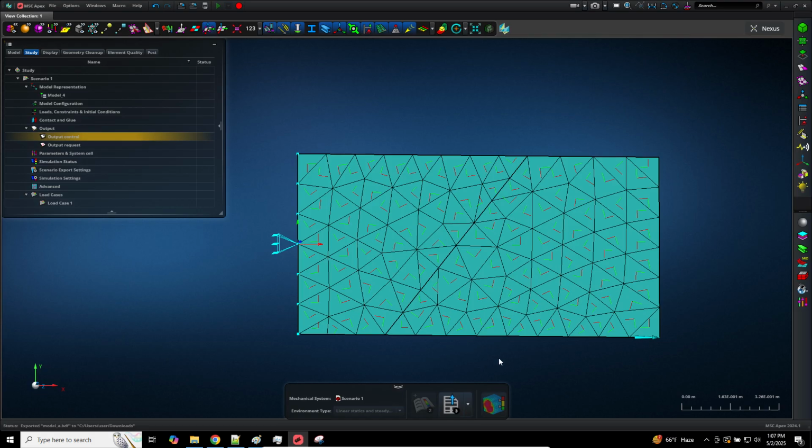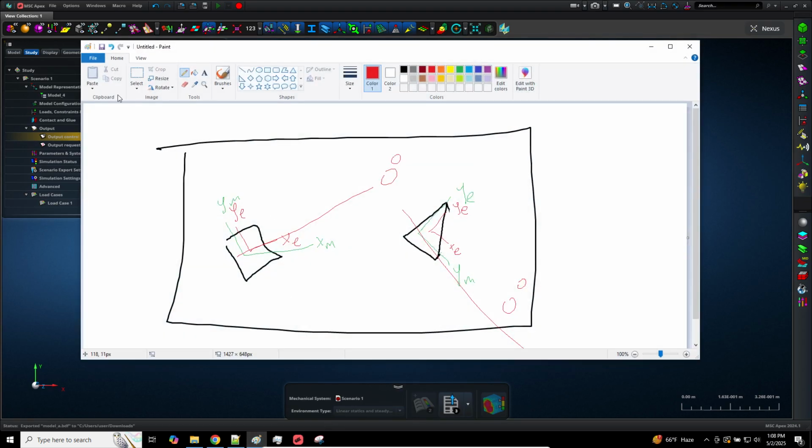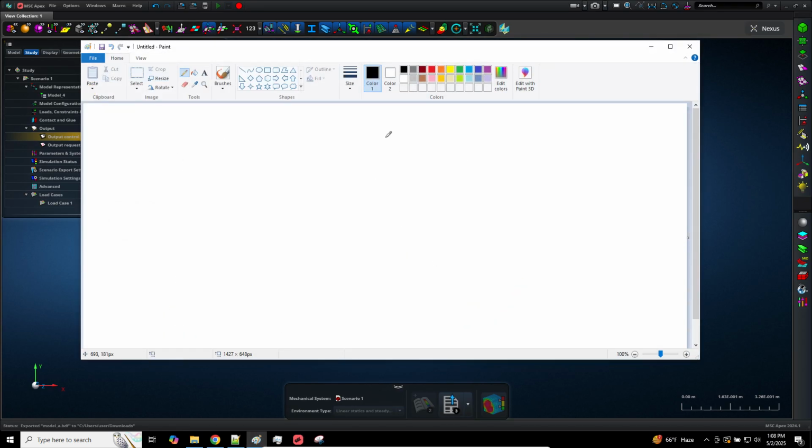Right now, what you see are the so-called element coordinate systems, but before that, let me talk about what a material coordinate system is. Let's suppose you have an observer like this. You told the observer, hey, my stiffness for E1 is this. It's maybe 100. The stiffness for E2 for this orthotropic layer is 200. You tell the observer, these are my values.